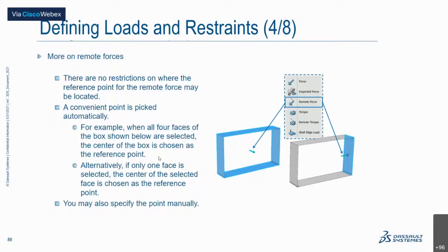Now, again, a little bit more about the remote force. If you select the total force and you want to apply it to a center point in that particular edge, you can just apply remote force, and once you make that selection, it will automatically select the center point. And if you select all the four edges, or all the four faces of it, then it will be the center force that it creates. So the system does it for you. It's generated internally itself.